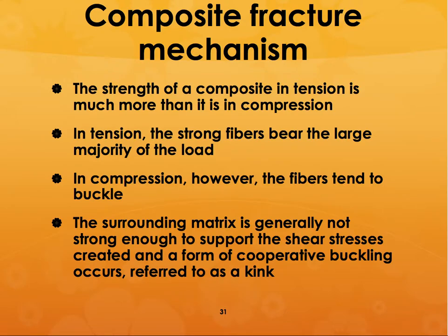Lecture 8. We are talking about how to analyze the properties of composites from basic properties. And for that, we need to understand what the fracture mechanisms controlling the properties of composites are. How will they fail when they are put in different kinds of stress conditions? One thing to note is that the strength of a composite in tension is always more than it is in compression, especially if you have continuous fibers.